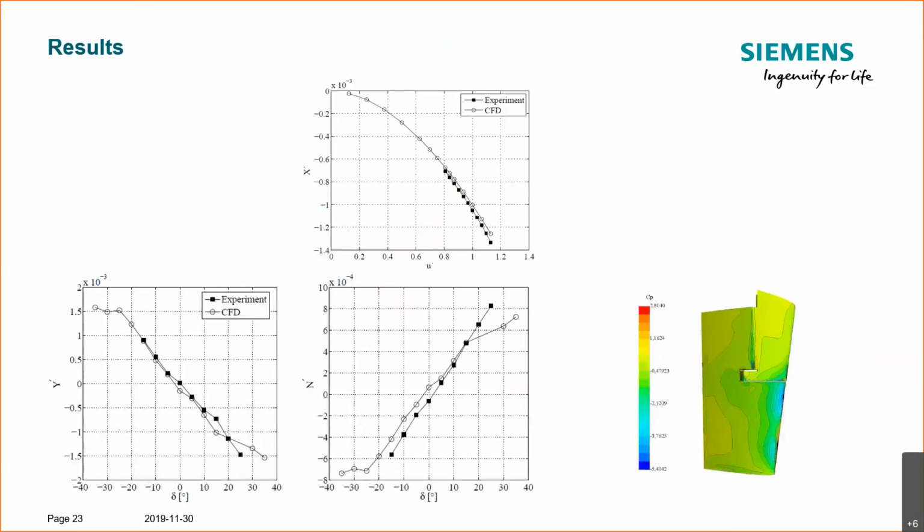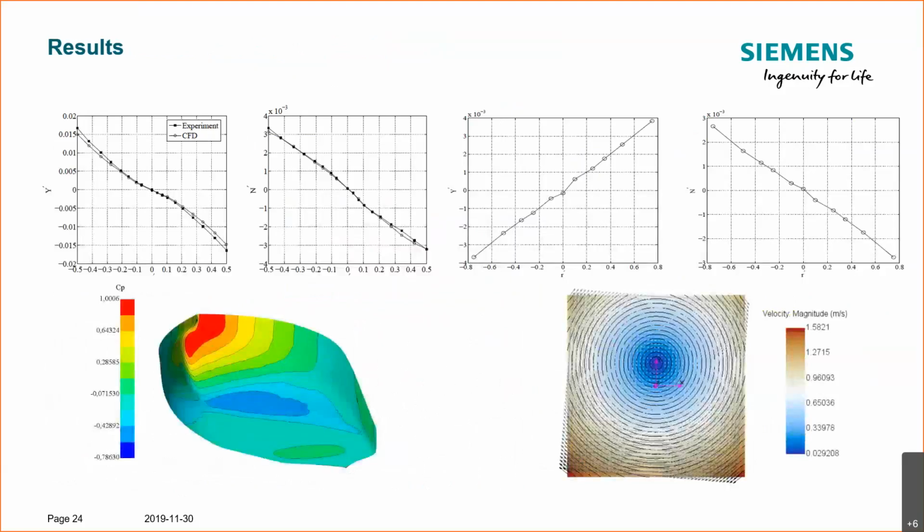So then we ran all these tests, resistance tests. You can see here results compared from CFD to HSVA experiment that's taken from the SIMMAN workshops, so publicly available data for the experimental side. Rudder tests on the bottom. Then the same is done for drift and yaw.